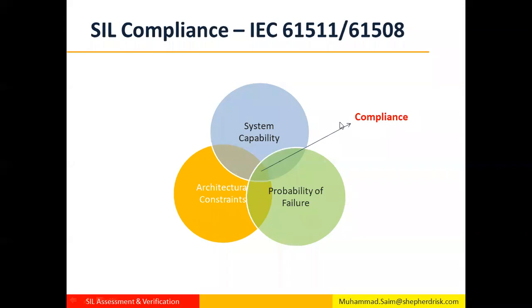And this tiny overlapping regime is the SIL compliance. If we are not meeting any of the three, but two, we cannot say that the function is in compliance with IEC requirements. So we need to meet all the three, but today we are going to talk about the PFD based on failure rate calculations.